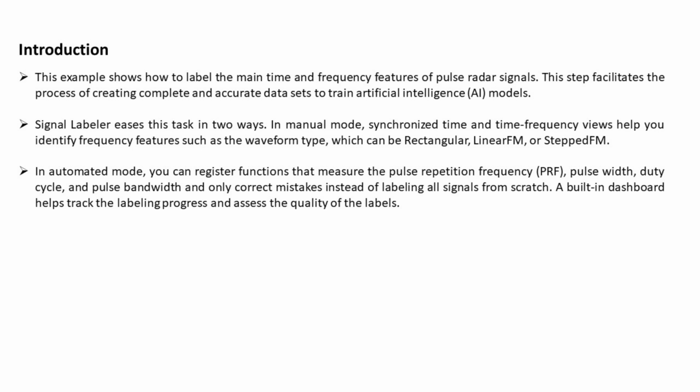In automated mode, you can register functions that measure the pulse repetition frequency, PRF, pulse width, duty cycle, and pulse bandwidth and only correct mistakes instead of labeling all signals from scratch. A built-in dashboard helps track the labeling progress and assess the quality of the labels.